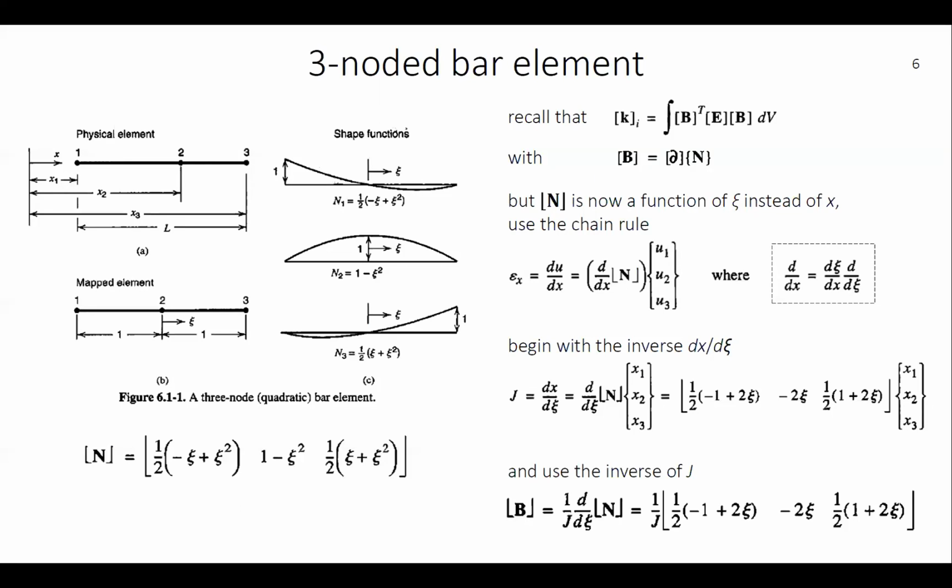when that happens. This is maybe more the risk for 2D and 3D elements, where you can come up with very distorted elements where the integration points are outside of the elements or in awkward positions of the elements.